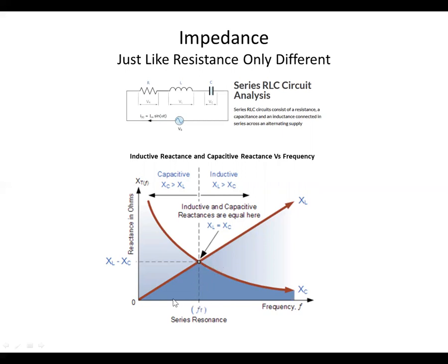So let's say we're on 40 meters and we want to operate right in the middle of the phone band. For a General, that would be 7.175 to 7.3, so about 7.230 or so is where we want the resonant frequency.